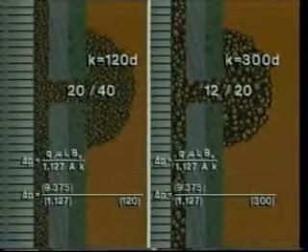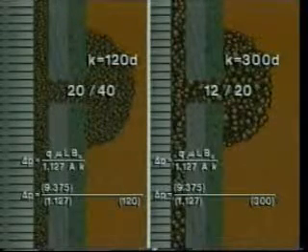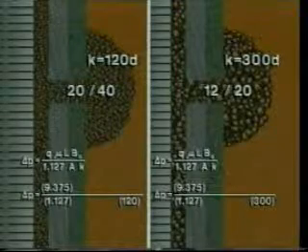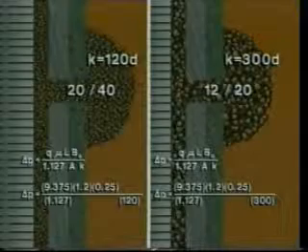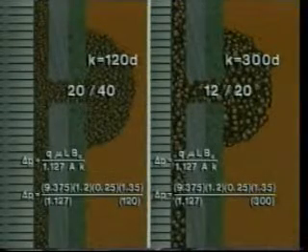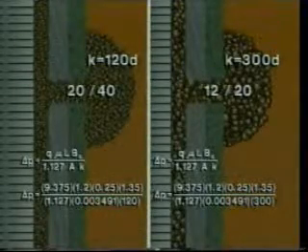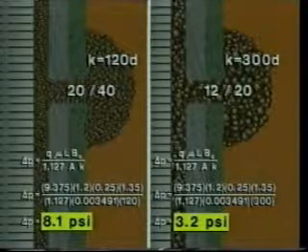Each perforation is producing 9.375 barrels per day. Assuming values for the remaining variables of fluid viscosity, perforation flow channel length, formation volume factor, and average entry hole area, the pressure loss can be calculated.